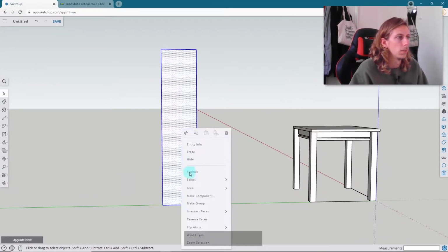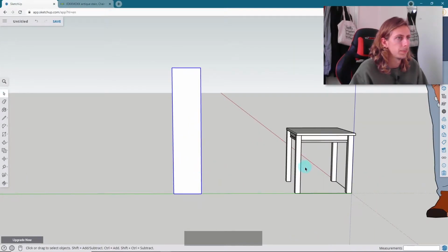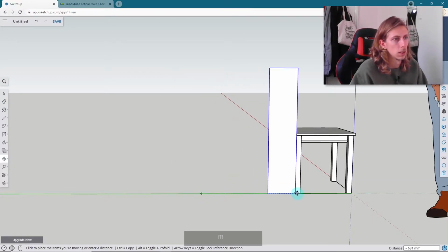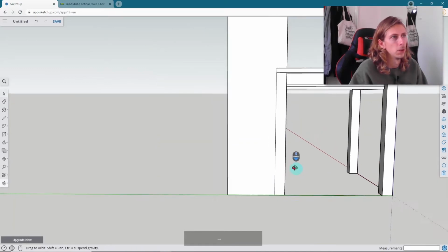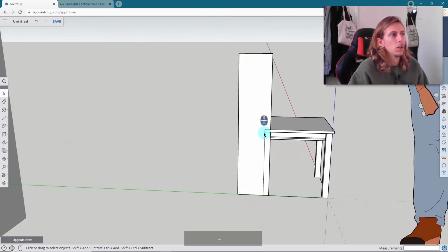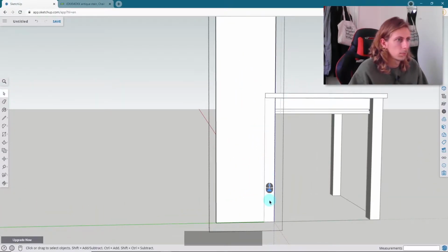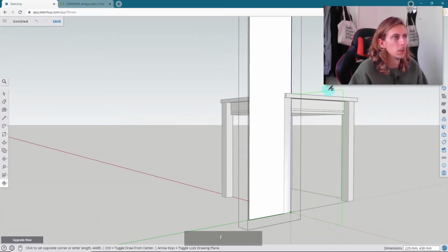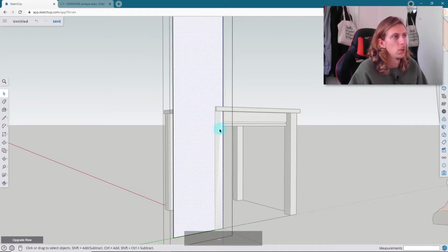I'm going to group this first off, and then move it over our existing leg, so we have a template that will show through a little bit. Then I'm going to come back into this rectangle and map this existing rectangle that is on a separate layer. So now I've got two separate faces within this rectangle.